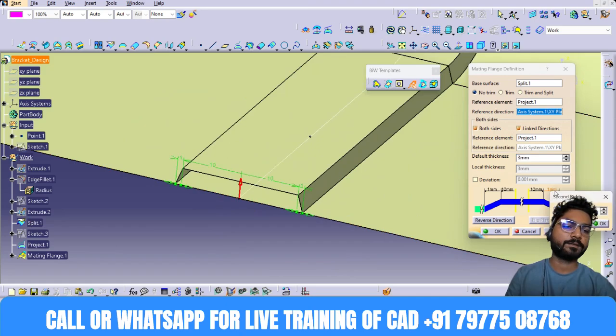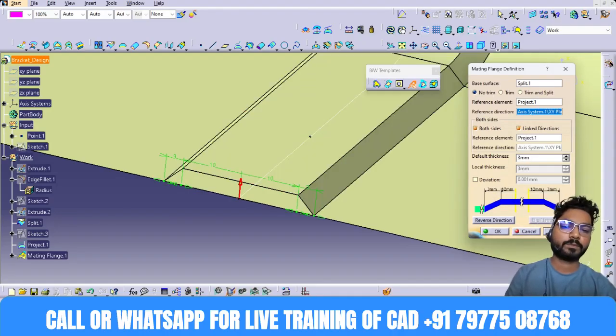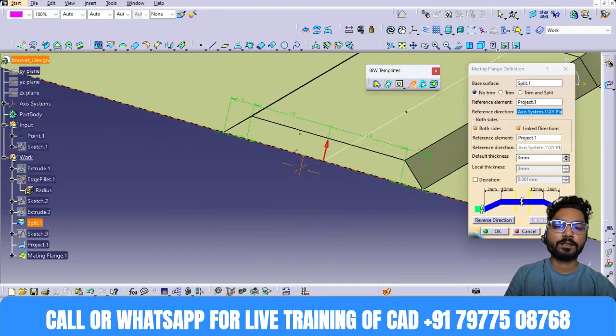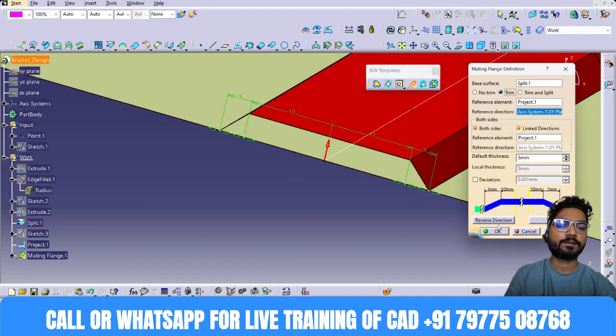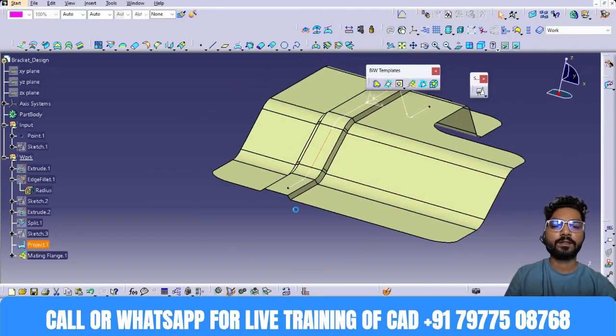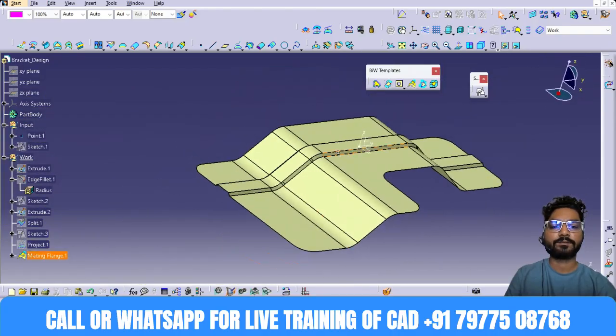I'll increase the draft to 3 mm, and this also 3 mm. Then this internal surface I don't want, so click on the trim button here and click OK. That area is getting removed. If you see this, what we have created is looking like this.